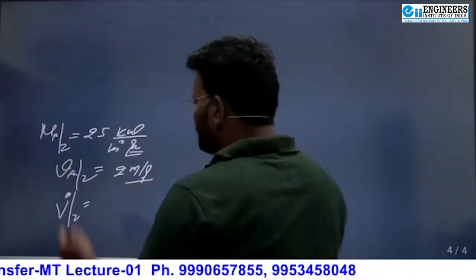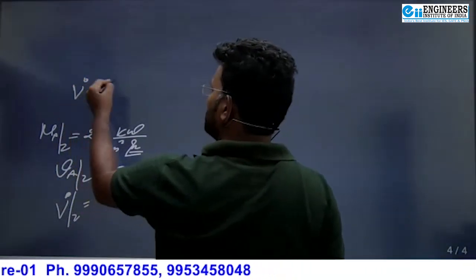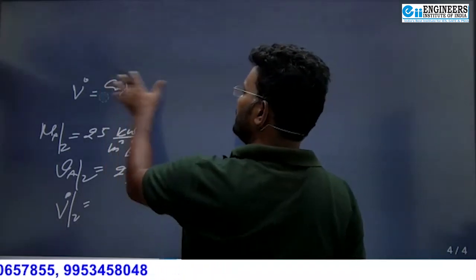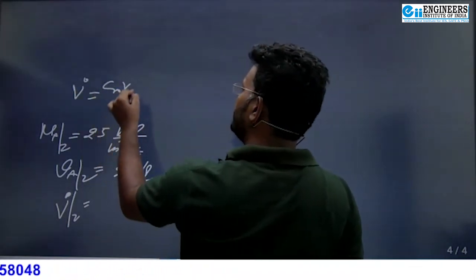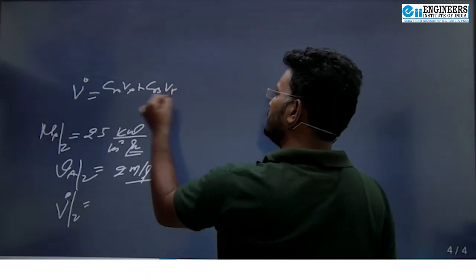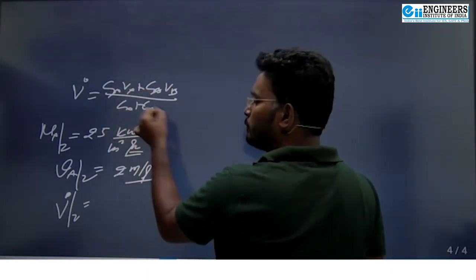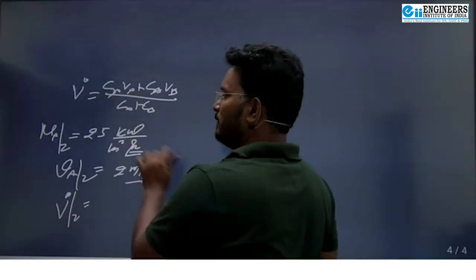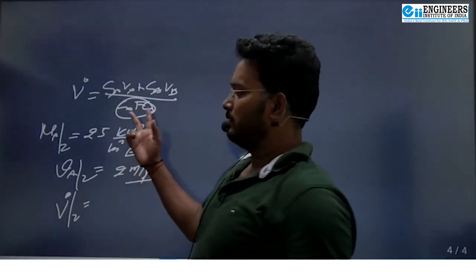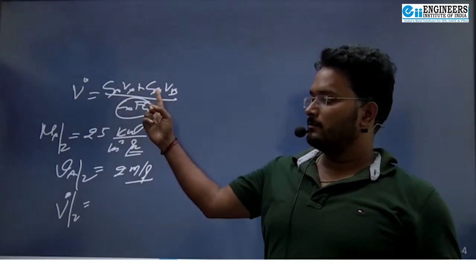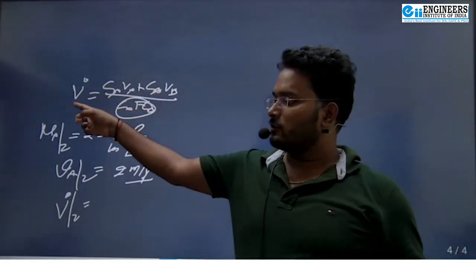I want to say, even the molar average velocity is what? CA into VA plus CB into VB upon CA plus CB total. Every term is going to change from point to point, na? CA, CB are all changing here, although CT is constant here. Velocity is changing. That's why V star may also change here.